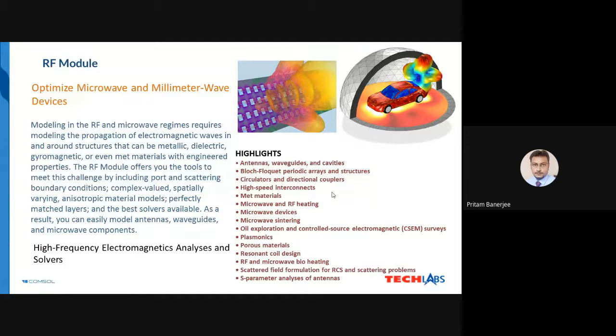For frequency domain analysis, you could compute the resonance frequencies, S parameters, near fields and far fields, Q factors, propagation constant, and antenna characterization through the frequency sweep.